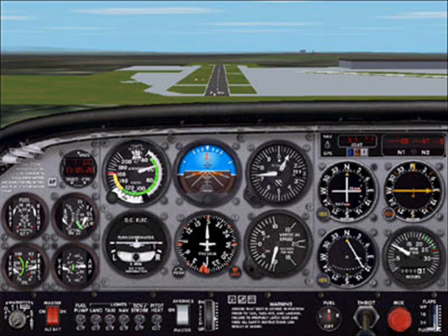When you're at flare height, raise the nose from its present attitude to about 14 degrees nose-up pitch. Hold that attitude until touchdown. Yes, you may hear the stall horn. More on this in the stall section. As you touch down, but that's okay since you're just inches above the ground.